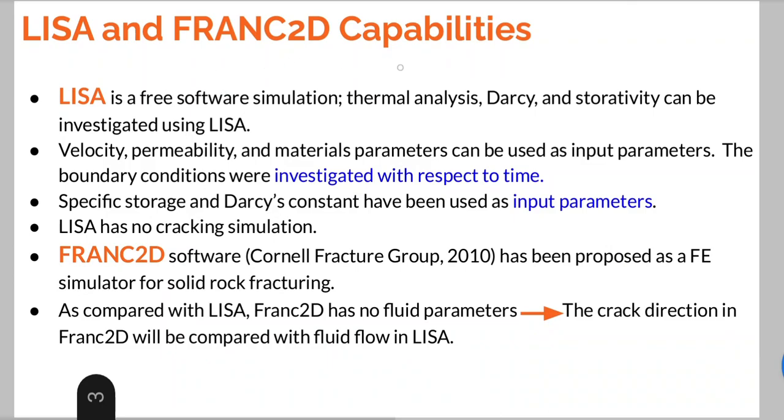LISA and Frank 2D capabilities. LISA is a free simulation software that can run different analyses such as thermal analysis, and Darcy and storativity can be investigated using LISA. Also, the velocity, permeability, and material parameters can be used as input parameters for the case study.